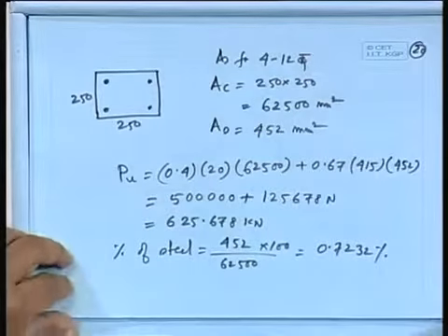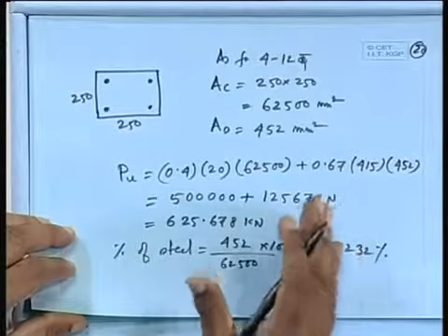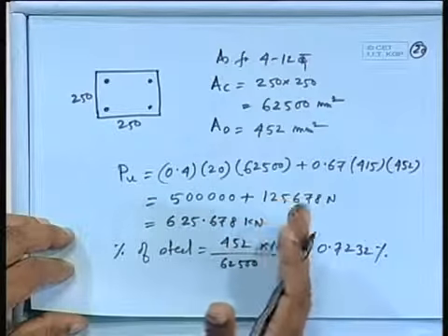And here generally we check those things. In design of reinforced concrete, the bending moment, shear force or axially loaded column, axial forces, all those things you will find it is very less. But even then you have to provide certain minimum reinforcement because of crack, shrinkage, creep, and a lot of other things also involved, stability. So from that point of view, you have to provide that minimum reinforcement or minimum dimension, and for that you have to follow IS 456.